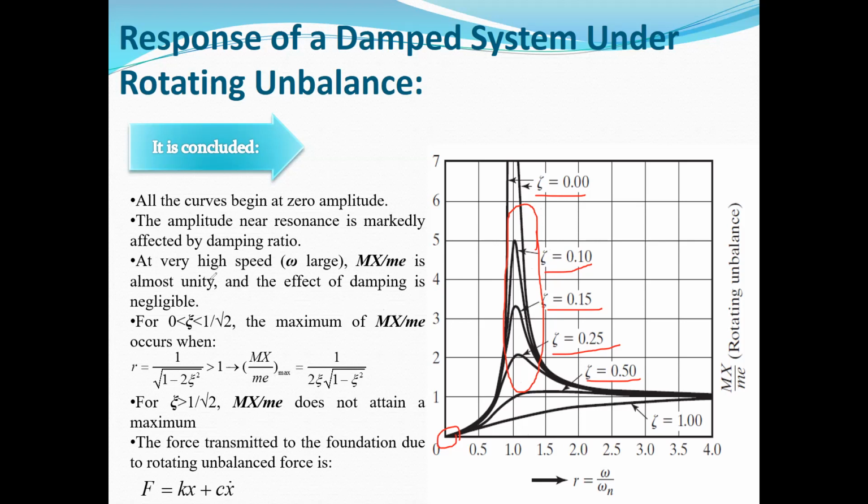The next one, at very high speed of omega, here in this area, you can see that the rotating unbalance is almost unity. In fact, when the frequency of the unbalanced motion increases, it will act as a static force on your system. So when the frequency of the rotation increases, you can see that the effect of the unbalanced force is like a static force. And after a while, you will see that the vibration motion will vanish, and we don't have any vibrating motion, and we will only have a deflection in the structure.